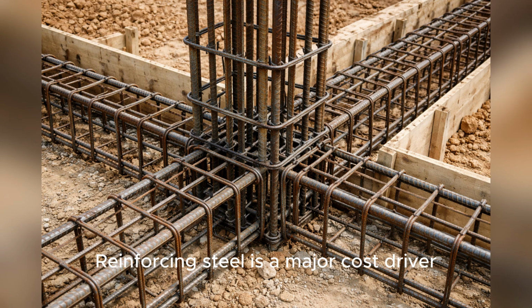Reinforcing steel is a major cost driver. DPWH computation converts bar size and spacing into kilograms per meter. Columns require vertical bars and lateral ties, while tie beams require top bars, bottom bars, and stirrups. Each bar contributes to total steel weight and cost.